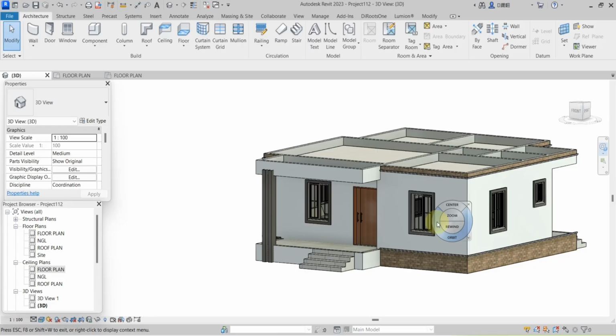Revit won't create the ceiling. This usually happens because the room isn't fully enclosed. Check for small gaps between walls or disconnected wall corners. Once the room forms a closed boundary, Revit will generate the ceiling successfully. You can't select the ceiling. If you are having trouble selecting the ceiling, press the Tab key until Revit highlights it, then click to select it.